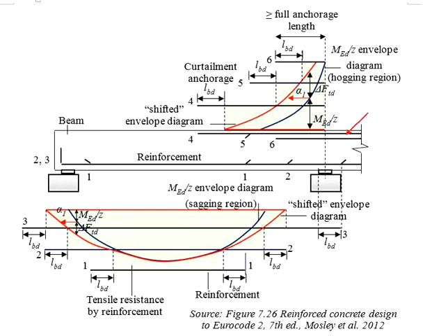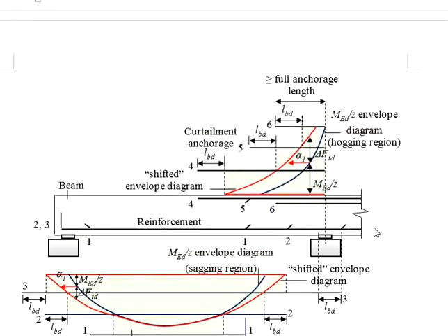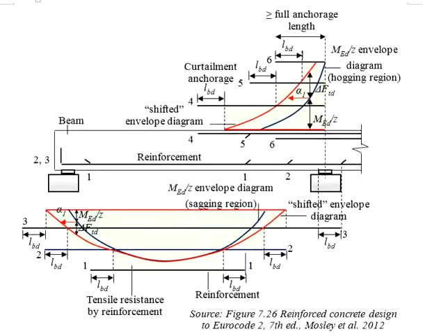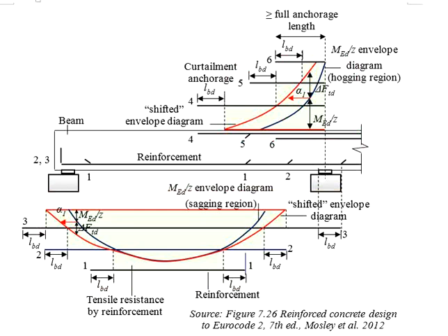The reinforcements are provided in order to resist those tensile forces as a measure to control the cracking in the member. And then the amount of reinforcement bar is curtailed in such a way that the resistance is always greater than what is required, ensuring along the entire beam span there are no regions with insufficient resistance provided by the reinforcement against the tensile force calculated.